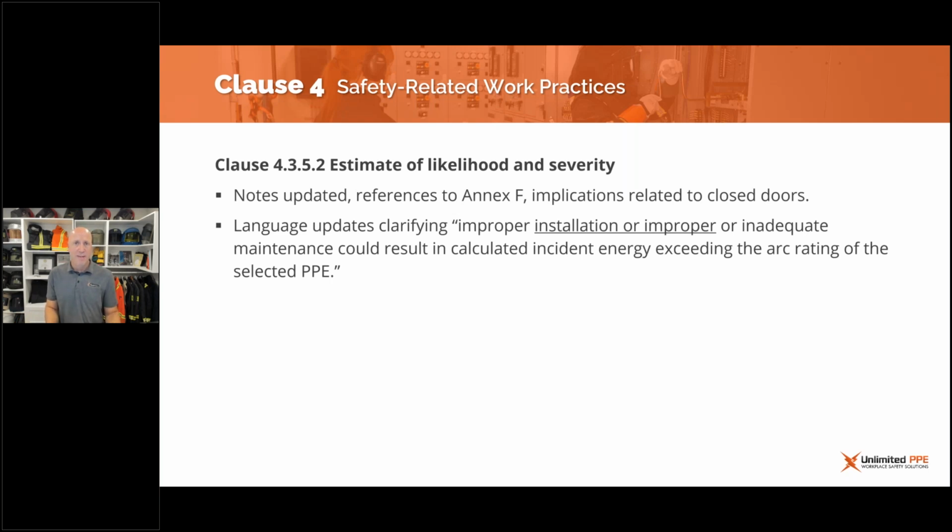An example of why that's important is the condition of maintenance may have changed. You might walk up to a piece of equipment and something's not right. I mean, you may have water leaking into the e-house. Using your look, listen, smell, you might smell burning of insulation. Well, that would immediately cause concern and a red flag that would identify to them that the condition of maintenance has changed, and therefore their risk assessment has also changed.